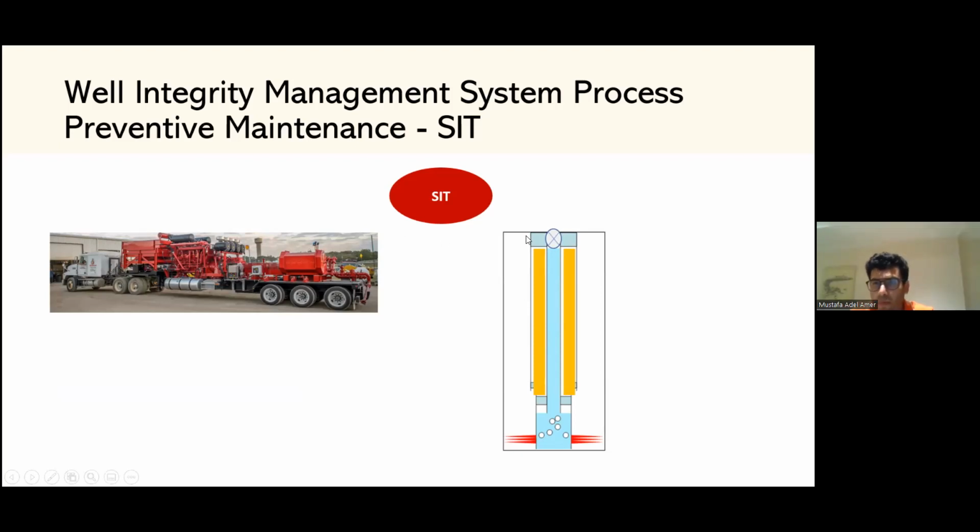And then you connect the pump to the B annulus. And if you have a C annulus, you do the same. And you test it, you record the volume of the fluid you add to top it up, and you monitor the pressure gauge during the test to make sure it's safe and not leaking. In practice, we do the SIT test every 4 years and the WIT test every year.